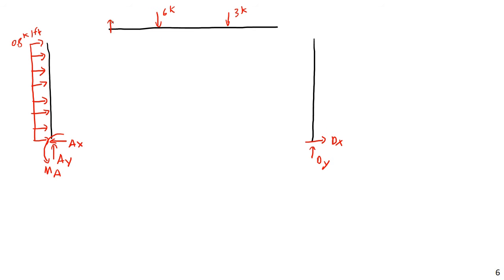I'm going to assume this is acting upward on this beam, and this was acting upward on this beam, or this end of the beam, or this joint. And then CY here. Now, again, I can assume whatever direction I want. I just have to assume compatible directions. So if this BY is going upward, this BY must be going downward. And this, in turn, let's see here.